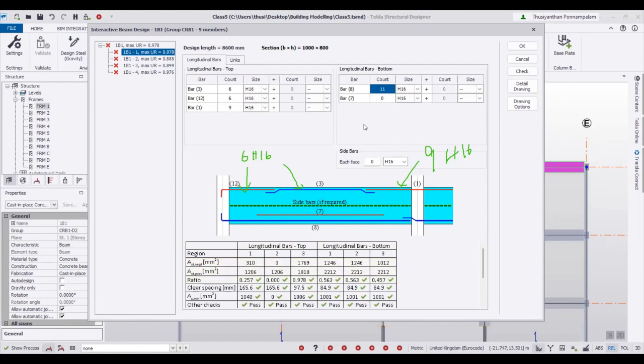We over provide, right? So I am going to reduce the numbers. Let's say I provide only 8. Right? So it becomes 1608. So it's almost okay. So I leave it 8, right? We don't need any additional second layer rebar, so it's 0.